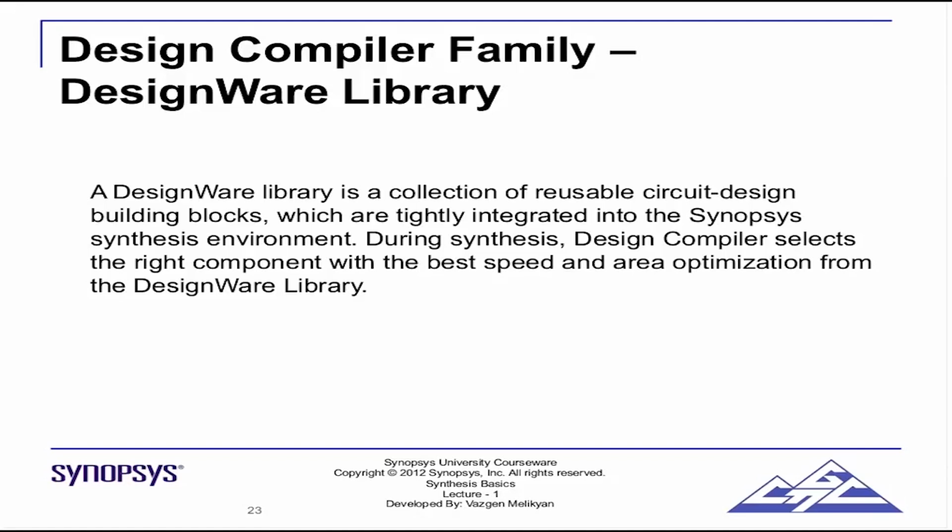So in the next lecture, let's review a bit what we saw. We saw what the process of synthesis is. It can be broken into 3 parts: translation, mapping, and optimization. The translation is simply conversion of your RTL code into a generic Boolean netlist.